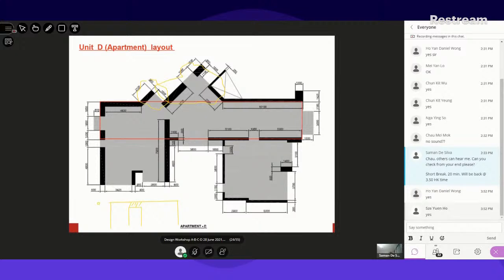What I am doing here is actually I'm trying to figure out what this is. Okay, there will be a sliding door here so that you can walk into the balcony. That sliding door is 2.1 meters high. Overall height is 3.5. There's a 1.2 meter wall section still continuing. So this is not a void. It is a void when you cut just above the floor plate. But if you go to the next level and then see down, you will see that there is a very healthy section. So this is the door.